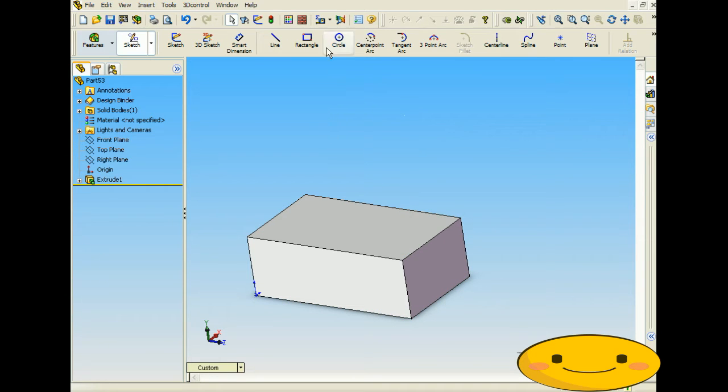And one other key feature that I like is when you click on one point, let's say this point here, you'll see that it gives you the box. It says where it is in the coordinate system. So it's x, y, and z direction. So that point has a coordinate of whatever it shows right there. Now, this is important with bigger assemblies. I deal a lot with the automotive industry, and what they do is they don't really use constraints in their assemblies. Most of the time, it's a positioning constraint.